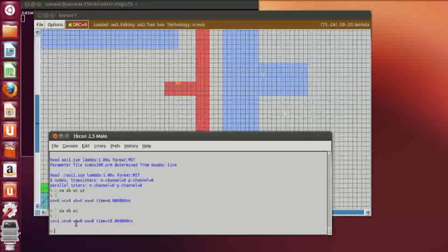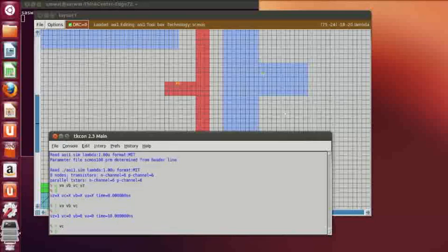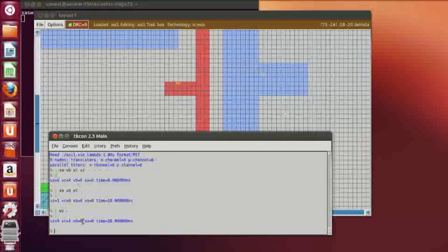So this is AND OR invert. Whatever the output from here, we'll get an invert of that. That is, we got 1. Let me give high value to VC. So certainly we'll get the output as 0. Okay, why? This is 0 0 and AND output will be 0. This is 1, so OR output will be 1 and the invert will be 0 again.